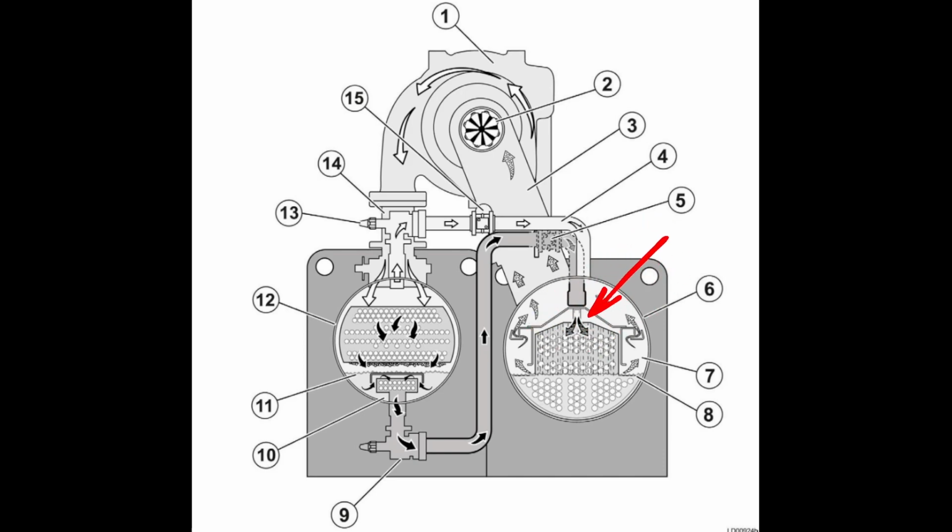So with this falling film, without going full blown into this, part of our refrigerant stream is being sent through a distribution rail. It comes through our liquid line, hits our metering device, and hits a rail to then distribute that refrigerant over the whole length of the evaporator. There's a spray system that mists that refrigerant over our tubes. So a good portion of our tubes are just getting misted on, and they're not submerged in the refrigerant.